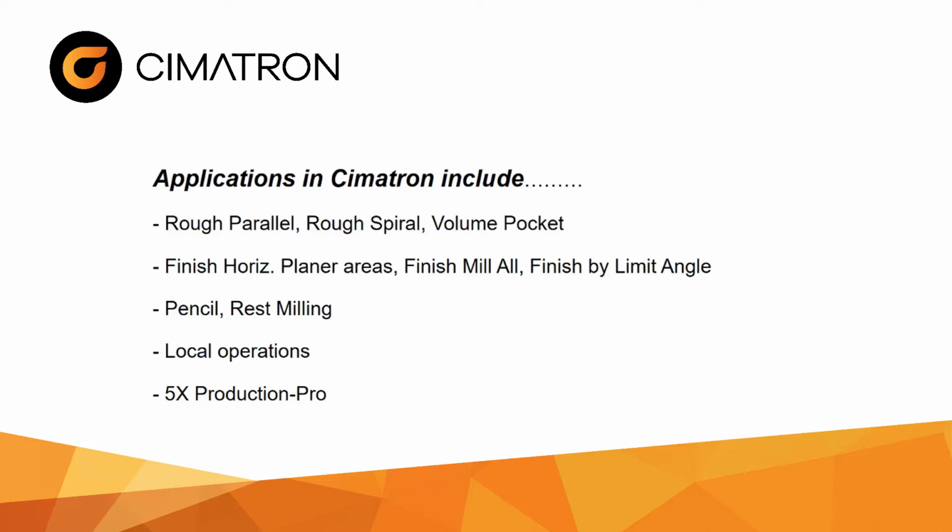Usually there are angle ranges, which we'll go over later, that are specific to each type of cutter. Most people will see the biggest benefits when you're able to stick in those angle ranges, use these types of tools, and put them into 5X production procedures. When you're able to do that, we're able to tilt the head and stay in the best angle range more of the time than we could traditionally in 3-axis. So 3-axis still has its applications. 5X has slightly more that it can fit in.